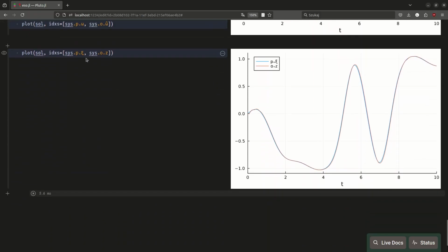And when we plot the actual total disturbance and its estimate, we can see that yes, it does estimate it. We can track it with some lag, which is expected, as this is especially visible when the total disturbance changes faster. But yay, hooray, it works.